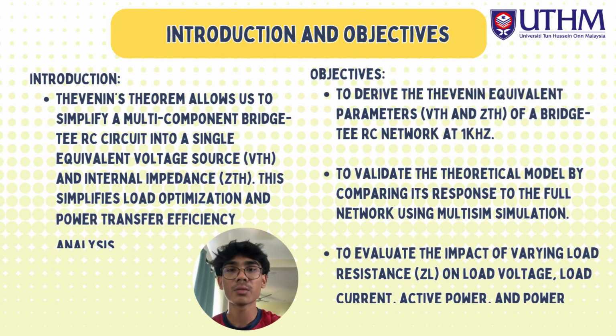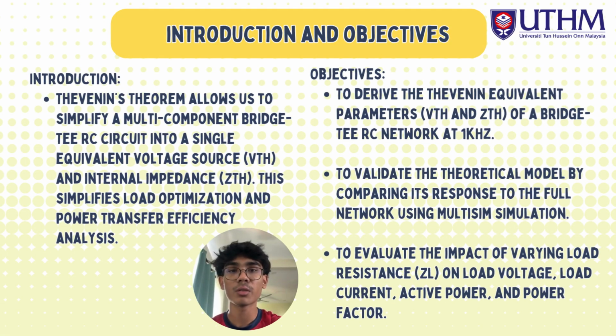Thevenin's theorem is one of the most important network theorems in electrical engineering. It states that any linear electrical network can be simplified into a single equivalent voltage source, called the Thevenin voltage or VTH, in series with an equivalent internal impedance called ZTH. In this project, we apply the theorem to a multi-component bridge TRC network.